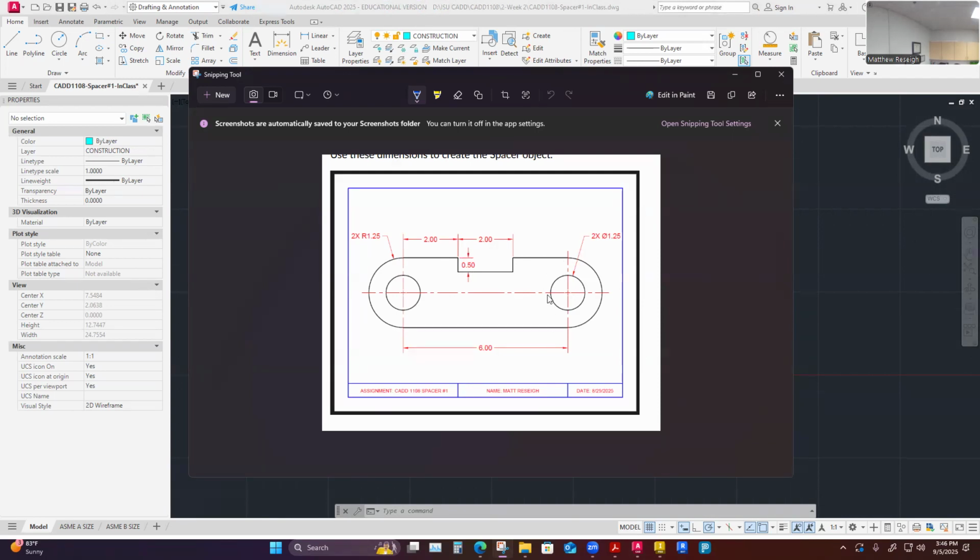What's the overall width here? Well, that's not immediately given, but it is kind of interpretively given. Sometimes that's not the best, because you might make someone have to do some math and mess up. I could have established the overall width with a dimension. I don't think it would have been redundant. However, I still have it here, even if it's not really recognizable, because I have a radius here. So this is to ASME standard, leader line and text here. It's 2 by R 1.25, pointing to this radius here.